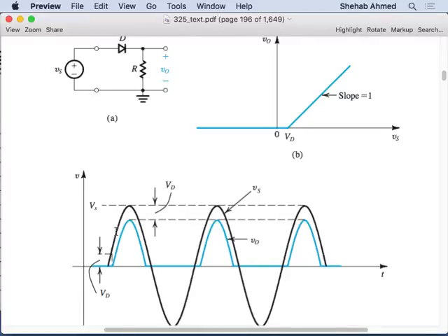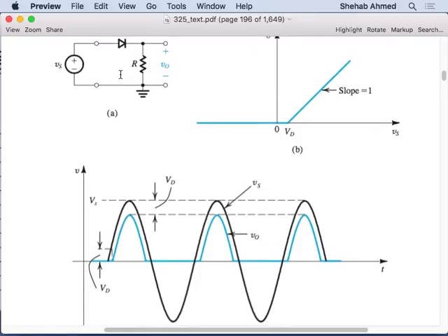If you look at that, isn't that inefficient of some sort? Yes, this V forward is a loss. Yes, it's inefficiency. You have something opposing you, and this something is a voltage source, and you're pushing current through it. So voltage times current is power loss. It's called diode conduction loss. In 438 we study that in a lot of detail.